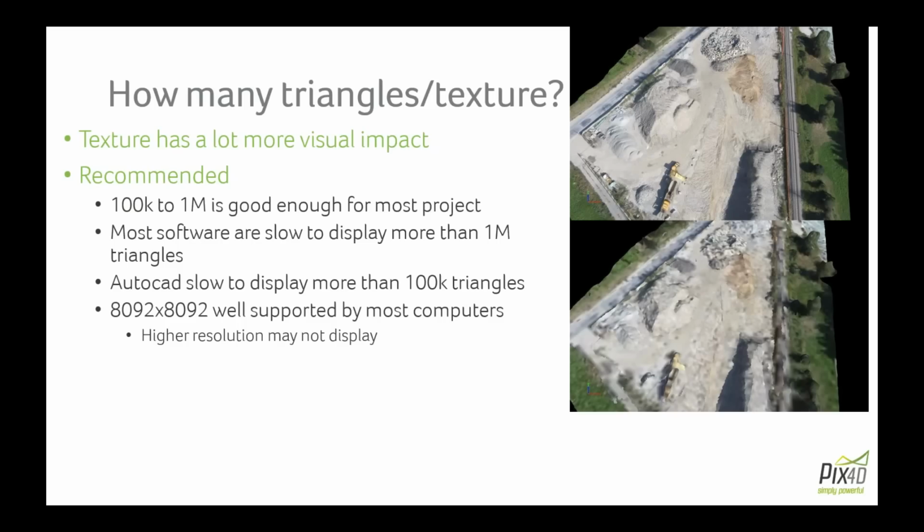But more important than that, there's very little software which is able to handle more than 1 million triangles. If you open most 3D software, let's say AutoCAD, which is a very good example, and you give it more than 100,000 triangles, AutoCAD is going to be very slow at loading them. And when you try to manipulate the mesh, it's also going to be a very painful experience.